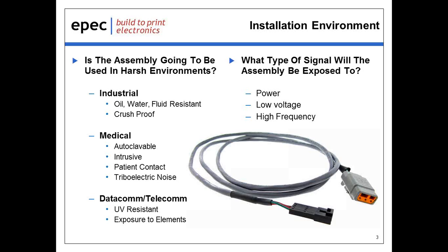If the cable is going to be used for patient monitoring, there could be a requirement to be resistant to triboelectric noise, or the noise that's caused when the assembly is moved in response to a patient moving or rolling over, causing false signals to get down to the nurse's station. In a datacom or telecom application, we may need to be concerned about UV resistance if it's going to be exposed to the elements. So something, again, we need to be careful of.